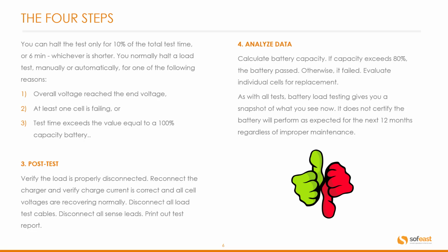Reconnect the charger and verify charge current is correct and all cell voltages are recovering normally. Disconnect all load test cables. Disconnect all sense leads. Print out the test report.